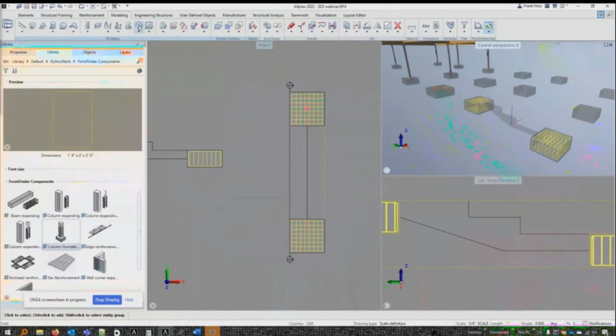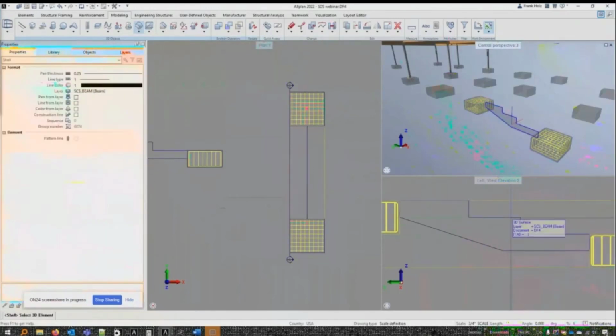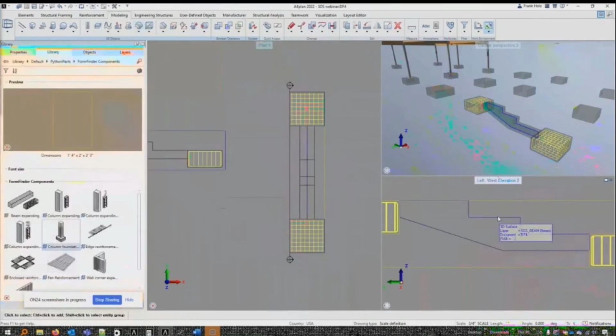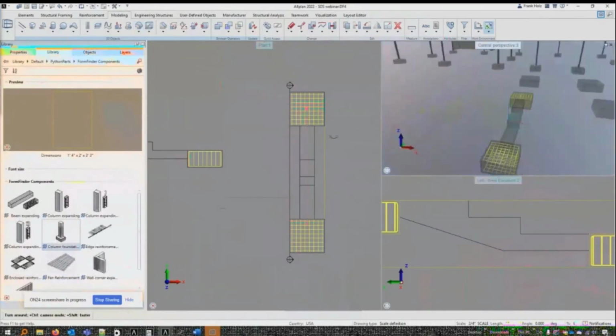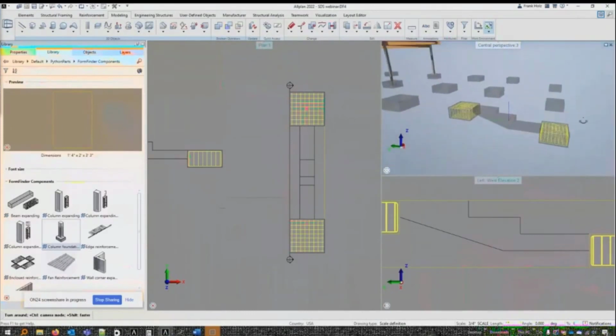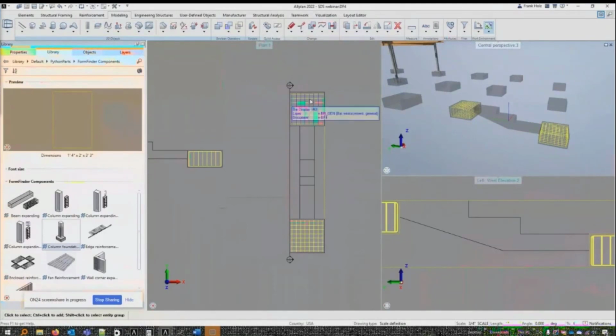Right now, though, I'm going to use the shell tool. This is great. It just lets you select any surface and then do a pop out from it, or in this case, just give some depth to an infinitely small section that we have here. And so now I have a little 18-inch wide step footing. You can see how easy that was to create. I just draw it in an elevation, draw it in a plan, extrude it through that dimension there. And as I said early on, just going to highlight it now, 2D to 3D workflow, that is what rebar detailers love about us the most. They're getting all this 3D, but the guys have been working in 2D all their life. They don't have to go to this whole new paradigm.